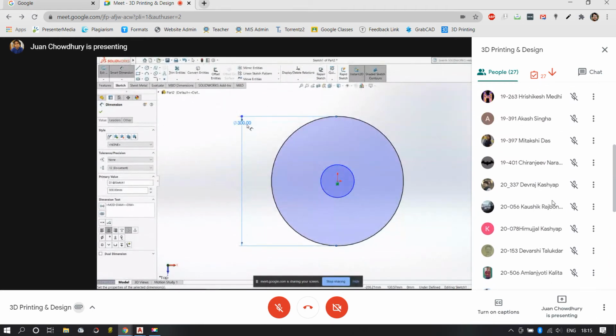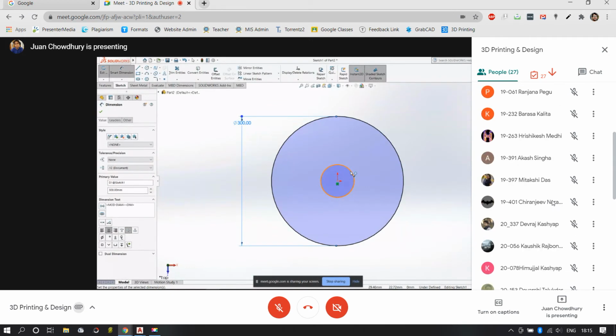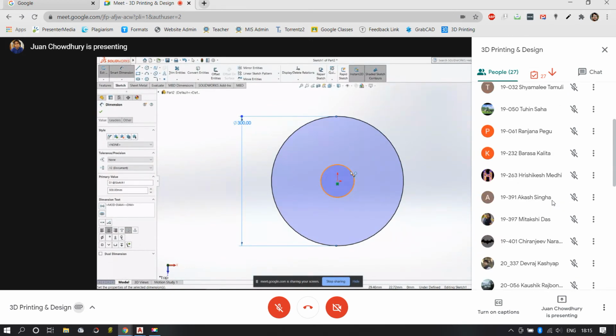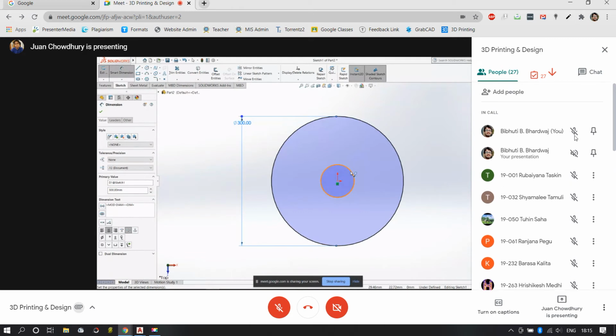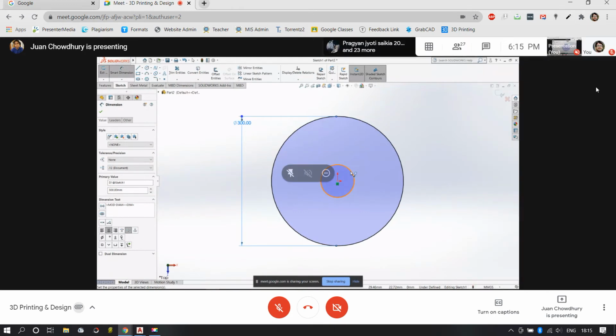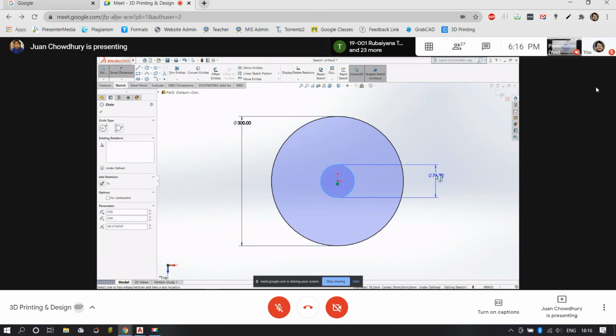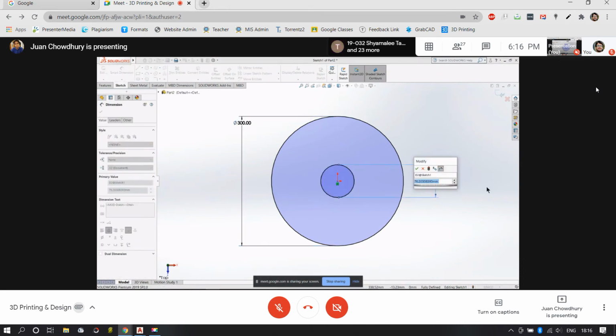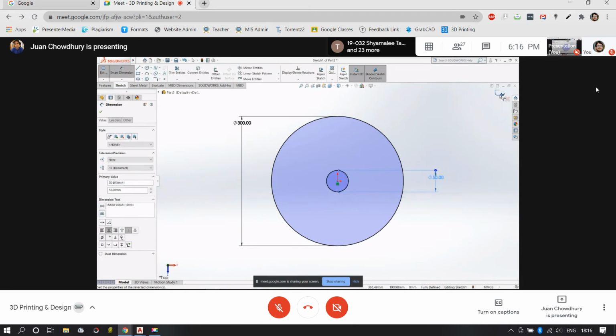I believe this feature is good because the inner circle, we did not dimension it earlier, so relative dimensioning has taken place. The larger circle did not surpass the smaller circle. I believe this is a good feature of SolidWorks. So keeping the smart dimension on, I'll click on the smaller circle and give it only say 5 centimeter of radius because I want it to have a hole in between. All right, there is an exit sketch button on the right, the blue one.